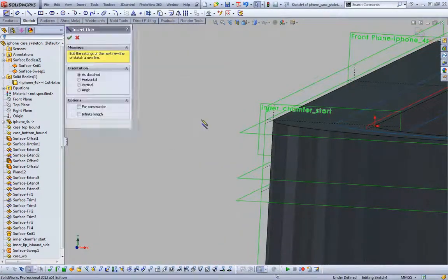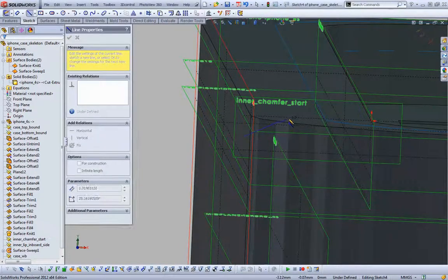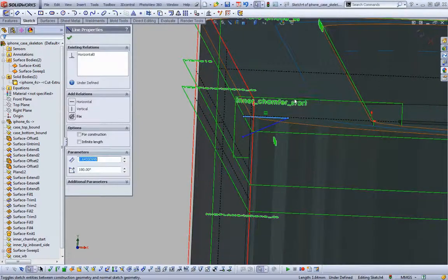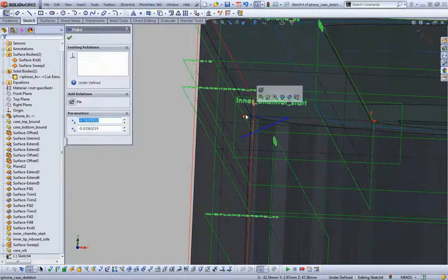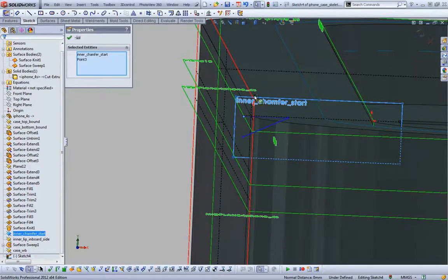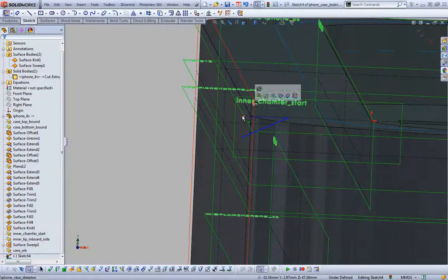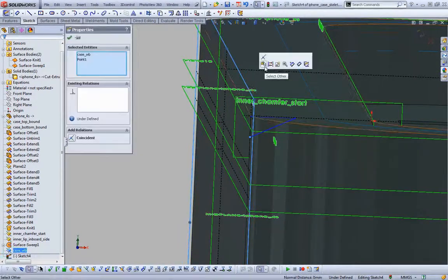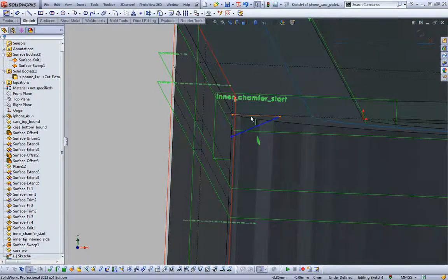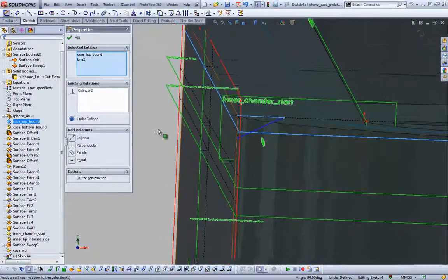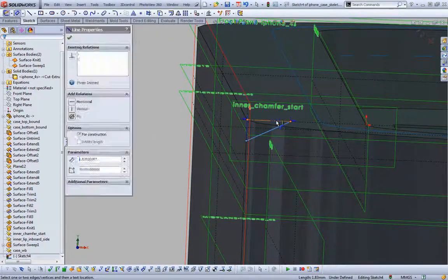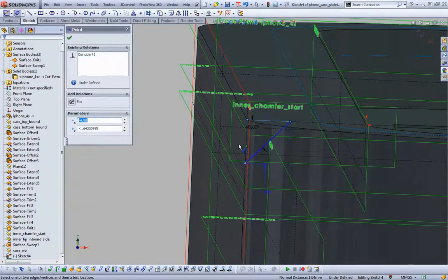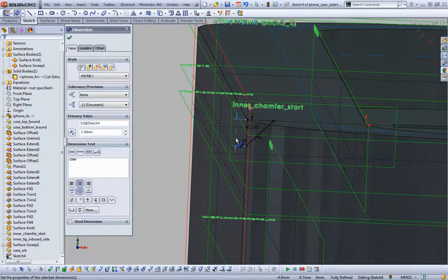So I like to use the planes created coincident to those geometry planes, to allow me to constrain sketch geometry to them. I believe that's more robust than using edges. Alright, this actually looks like it's a little bit steeper of an angle, so we'll do 45. And then let's do 1 again, just for giggles.